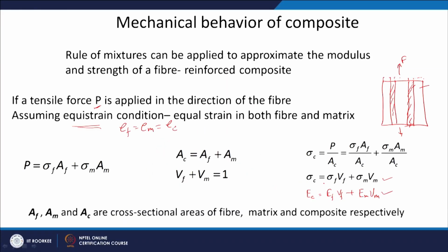Okay. So, depending upon what is the volume fraction of fiber, it will have that much contribution to the total composite stress or strength, and similarly what is the volume fraction of matrix, that will contribute to the total strength of the composite. Now, if we want to see the stress strain curve in terms of composites.